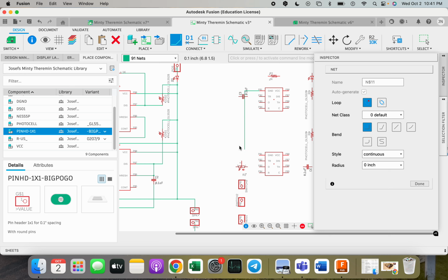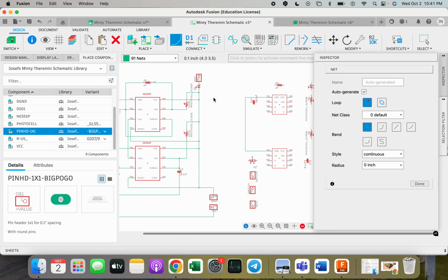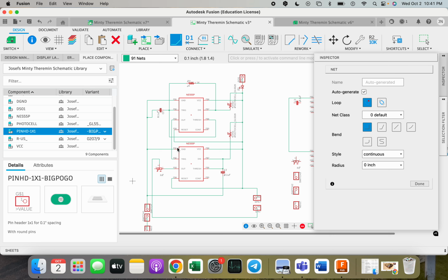and every time I want to change a corner, you'll see I'm able to do one corner, but I don't really have control of where I want to place it. So I can click and say that's where I want my line to be, and then I can come down in line to my second pin here. And we'll pop up that little circle, noting that it's connected on there. So that's pin 1 to pin 1, and now we've got to attach pin 1 to the capacitor.